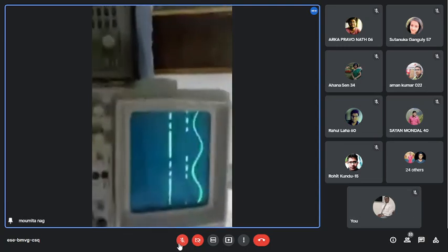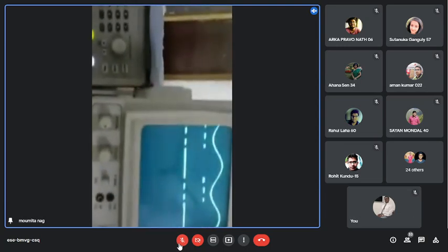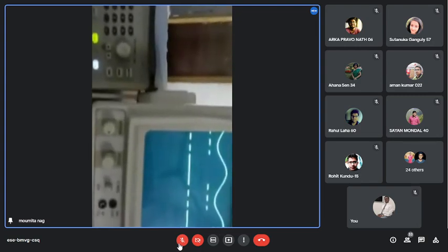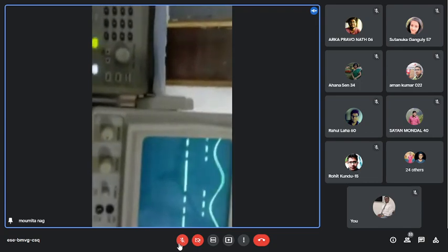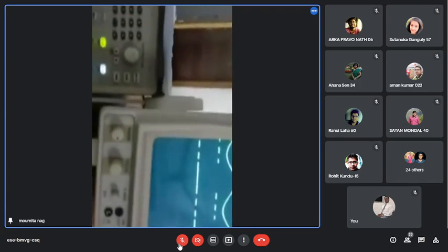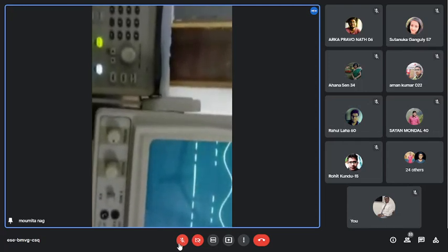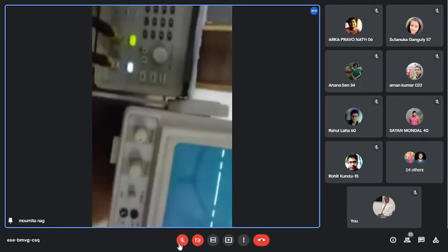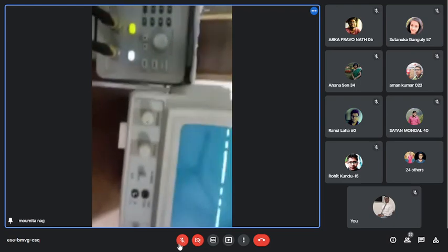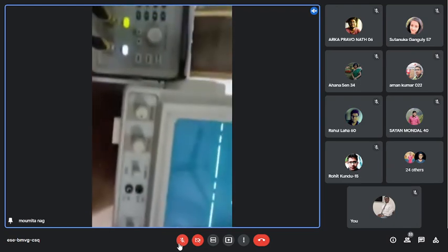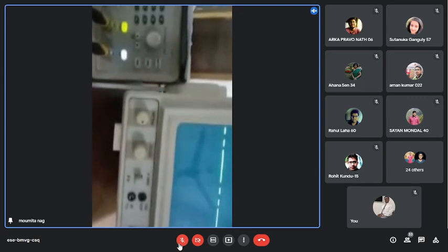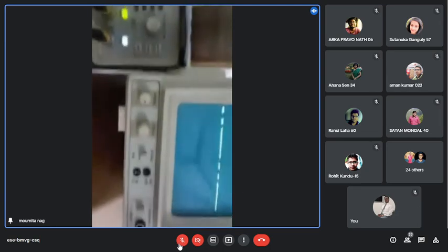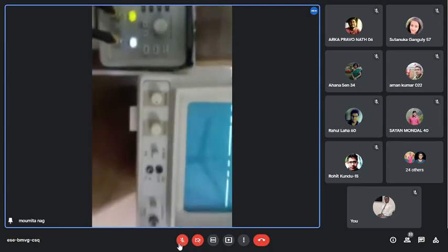Okay. This PWM signal will go to the input of timer 2 as trigger. See the circuit. This PWM signal will go to timer 2 at pin number 2 as trigger input. When this signal goes, then at the output of timer 2, we will get the PPM output. And this PPM output will occur at the negative edge of the PWM signal. See that?